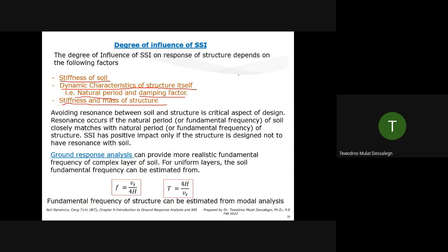Sometimes when you analyze a structure, you may observe a phenomenon like resonance. Let's say when you do your SSI, you get significant output on some floors. The acceleration level at each floor, or the response spectra we develop at each floor, which help us design the framing system in that location, may be significantly high.